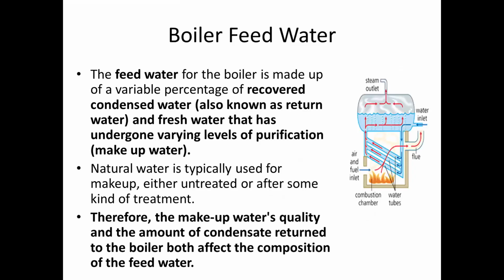So we talk about boiler feed water. It is made up of recovered condensed water, also known as return water, and fresh water that has undergone varying levels of purification, which is our makeup water. So it is a combination of condensate water and our makeup water. Natural water is typically used for makeup, either untreated or after some kind of treatment.